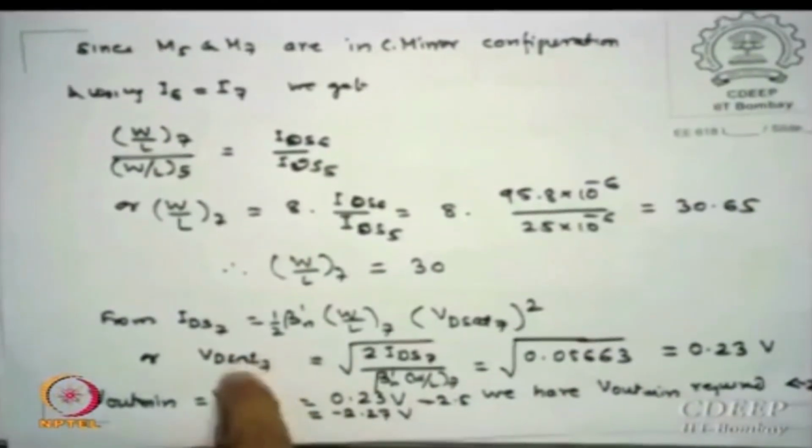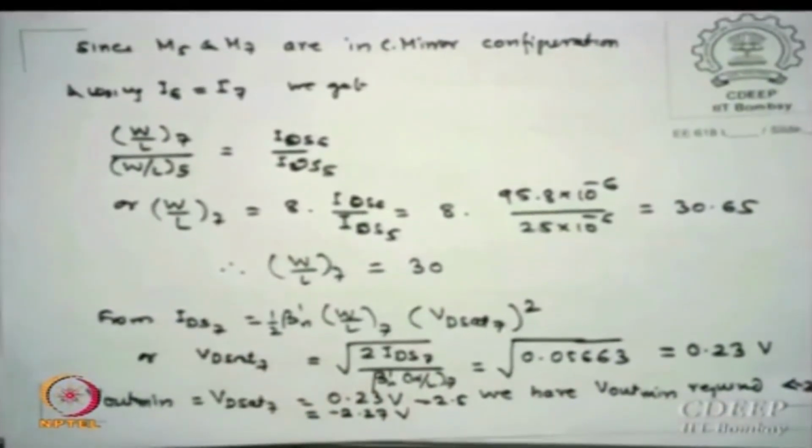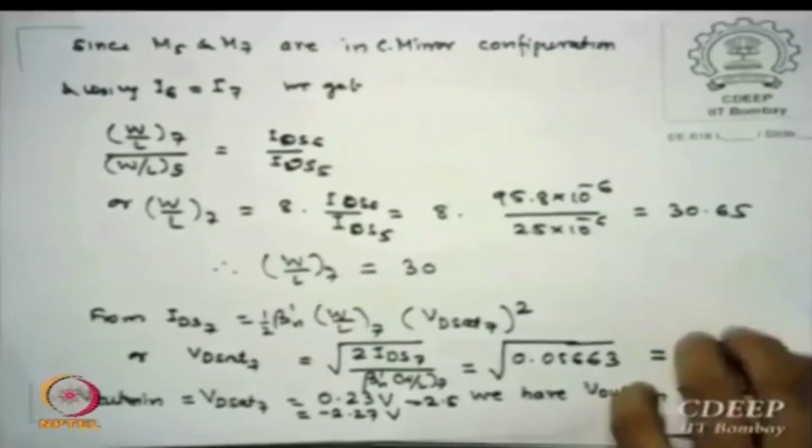The device is still in saturation. Even with this it will still remain in saturation, so good enough. And we are improving the lower margin of the Vout, so that is a larger swing. There we increase beyond 2, here we reduce minus of that, so very good. Okay. So in some sense we are getting better swings than what we were actually asked to do.